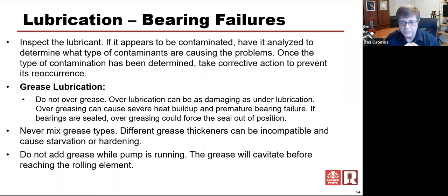You will find that sometimes on big turbines, like at a power generation plant, they may use a spray bearing lubrication, but normally it's an oil bath, where as the balls are going around on a bearing, towards the bottom they splash into a bath of oil. You never want the oil level too high on that bearing surface.